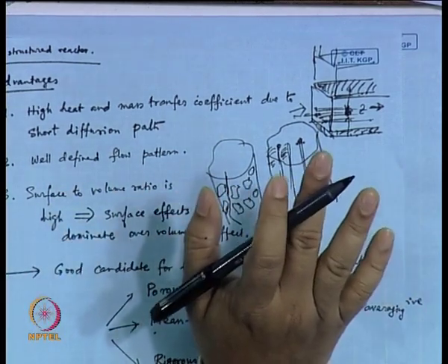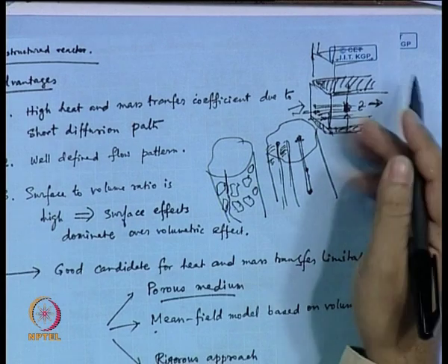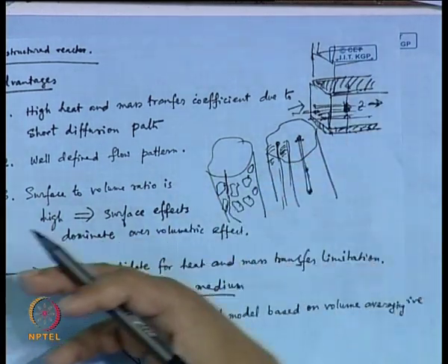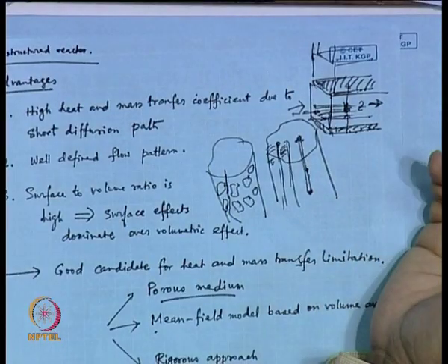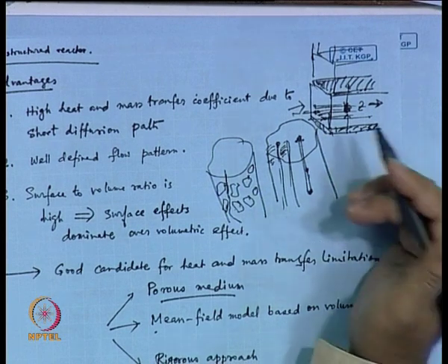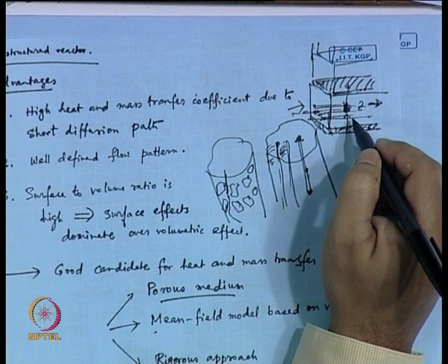because you want to avoid the side reactions. Okay. Now, if it would have been a packed bed, you can have a similar arrangement in place. You can have a packing and then you have a heating layer around, but since it is a packed bed, since this flow pattern is not well defined, what you end up with is a temperature gradient within the solid.